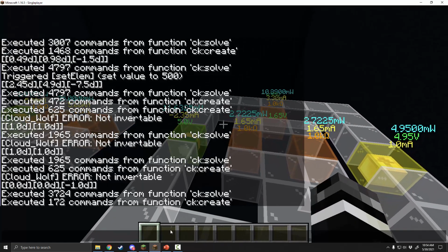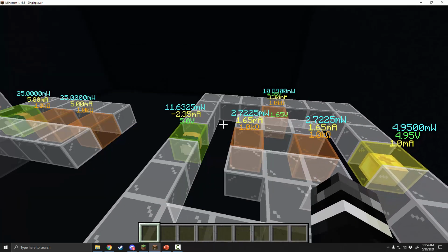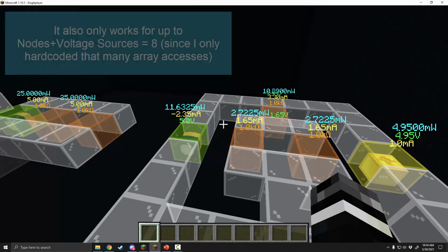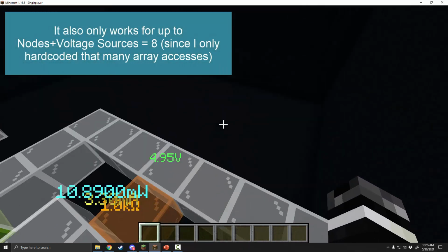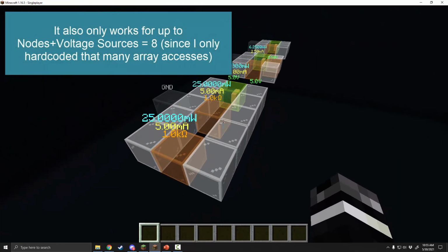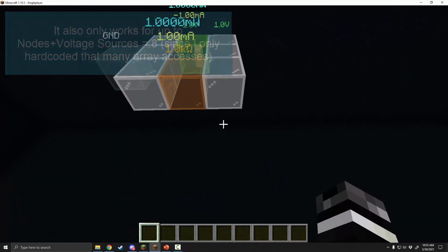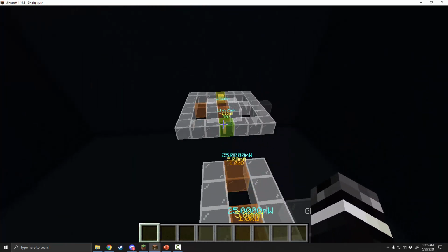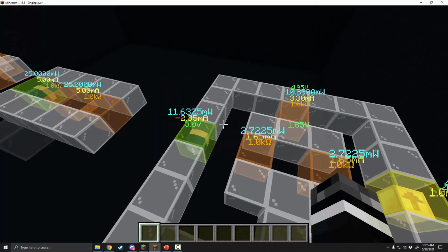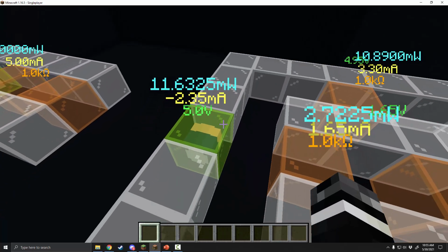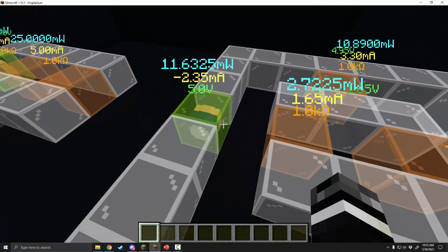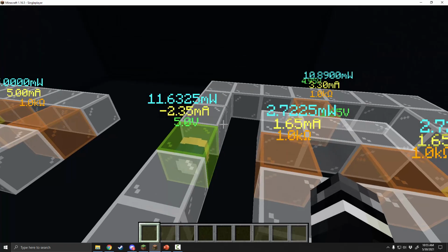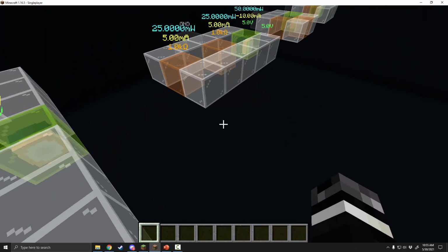And I even checked it with the MATLAB program, and yeah, the matrix inversion algorithm doesn't like it, because when you have the bigger arrays, the more sparse arrays, you're going to have a lot more zeros involved with the MNA method. And when you have a bunch of zeros, that's a lot more likely for this matrix inversion method to freak out and give you the wrong answer.